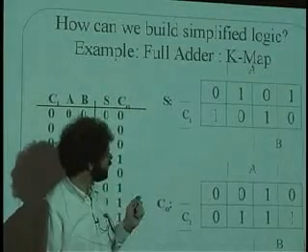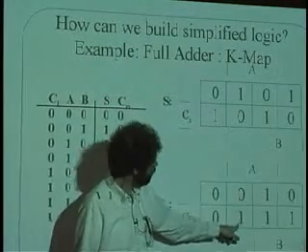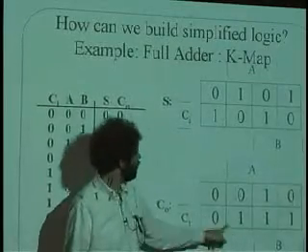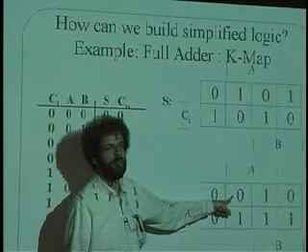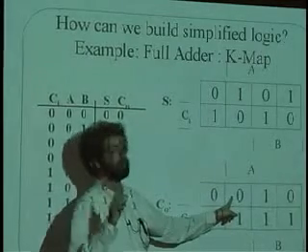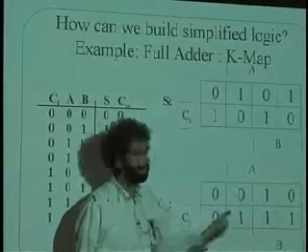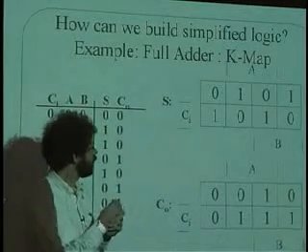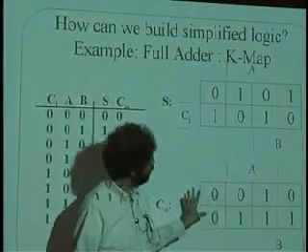Now what's the characteristic that a checkerboard like this has? Well, it has an amazing thing. First of all, if I'm in any square, this corresponds to A equals 1, B equals 0, because I'm not in the 2 columns with B, and C sub I equals 1. That's this place here. If I move in this direction, how many of the input bits change? I go from here to here. Only 1. If I go from here to here, how many change? 1. Here to here, 1. So whenever I move to a cell that's right next door, across a border, only 1 bit will change.